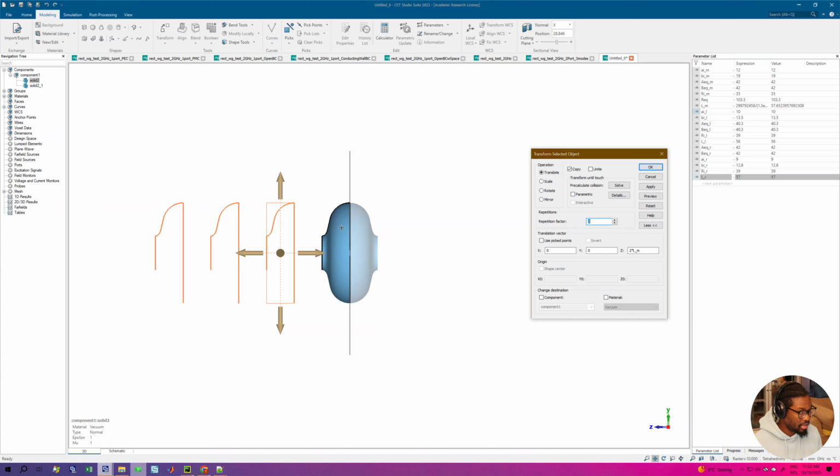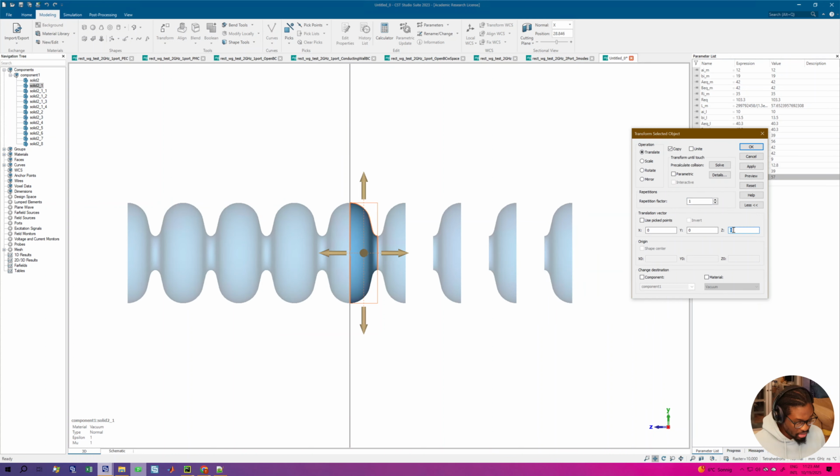Yes. And now for this, I just have to do the same thing twice. So for this, I have 2 times LM, and I need to copy it, and I need 4 copies. 4, exactly. Yes, so I apply this, and then in the other direction, so minus 2 times LM, preview 4 times.